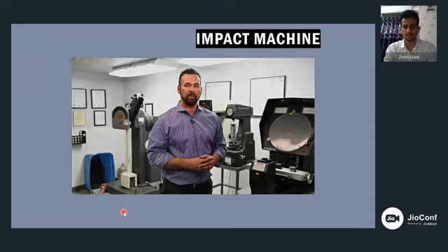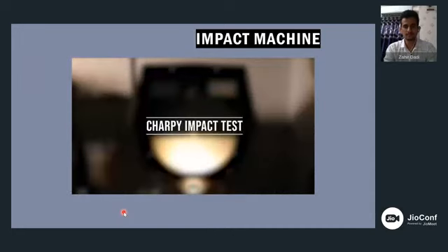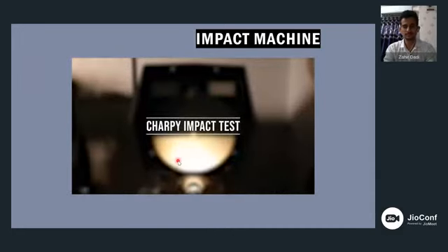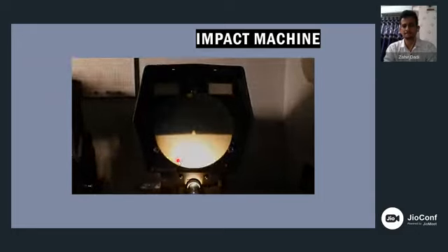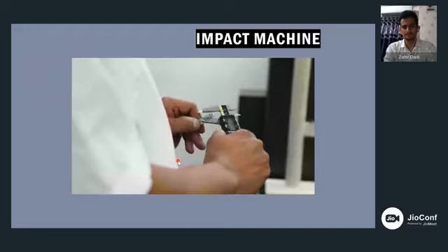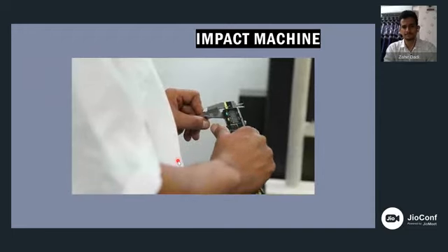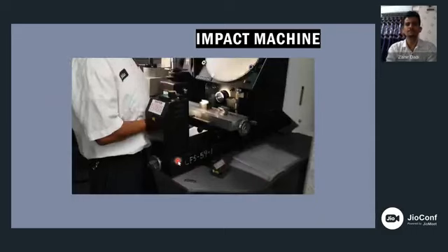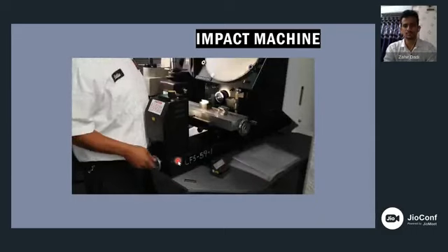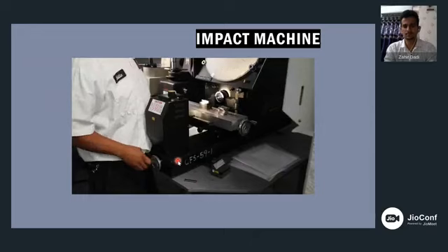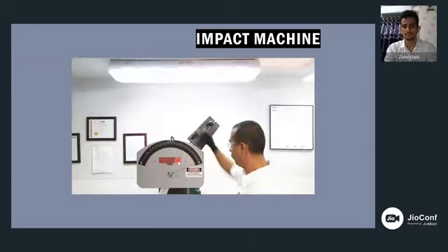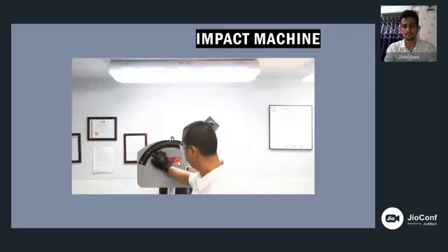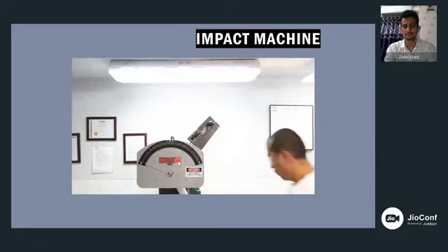The Charpy impact test, also known as the Charpy V-notch test, is a standardized high strain rate test that measures the amount of energy absorbed by the material before it fails. The sample used is machined to a V-shape notch. This is known as a Charpy specimen. It is cut at a specific dimension to meet the relevant Charpy testing requirements. The measurement needle is manually adjusted to 0 on the scale, ensuring that the energy absorption can be properly recorded at the point of impact.